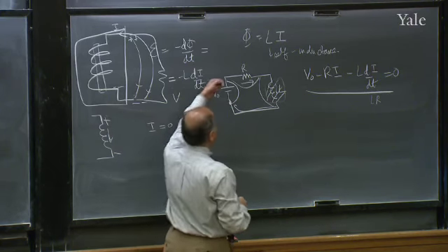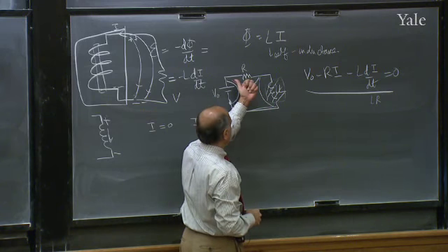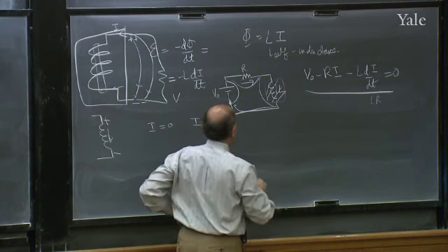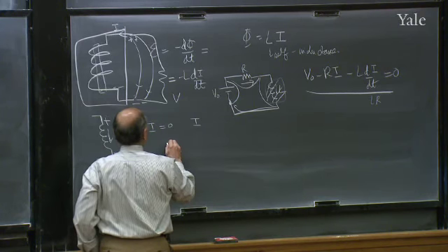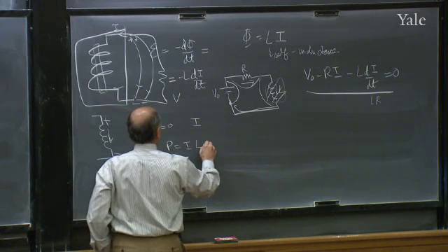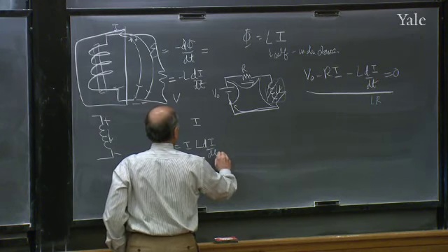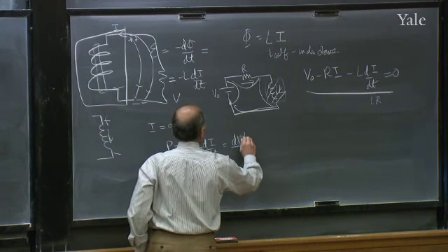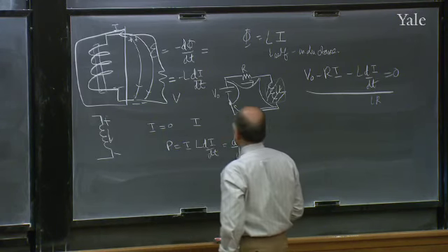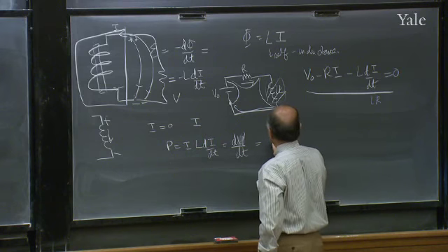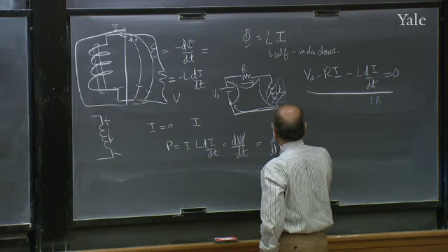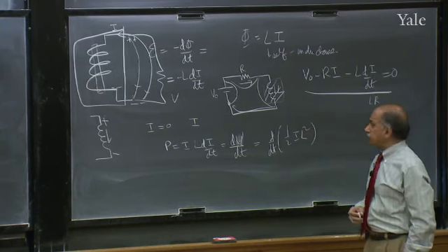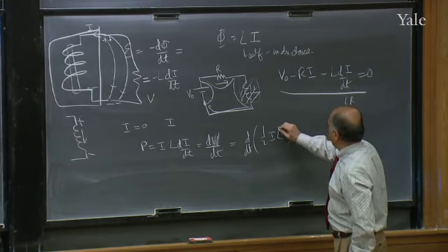Because when you start driving the current, it's opposing you with a voltage L di/dt, and you're ramming the current up in spite of that opposition, so that the work you do, the power, is I times L di/dt, which, if you like, is the rate of change of energy. But I times L di/dt is d/dt of 1/2 L I squared.